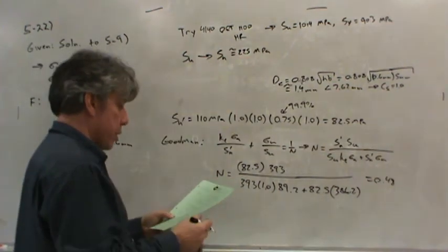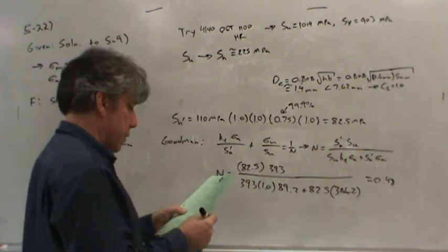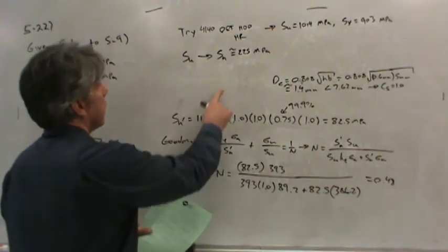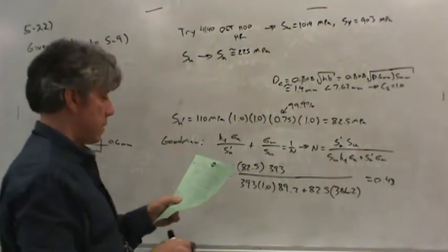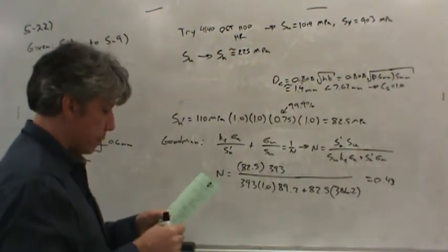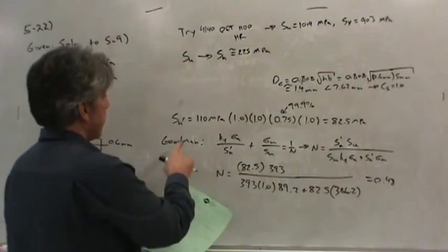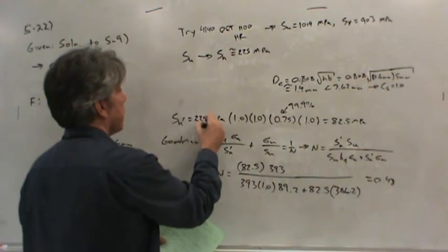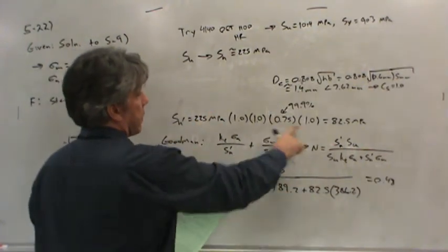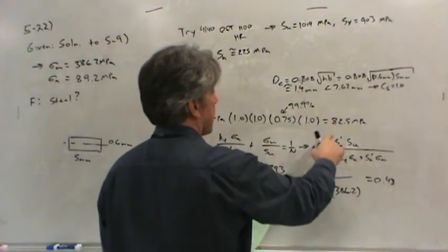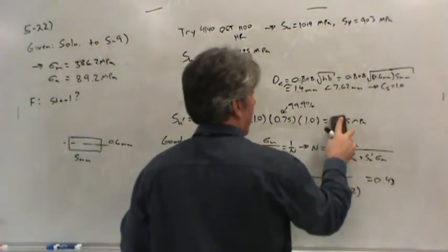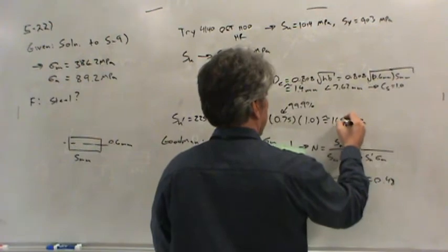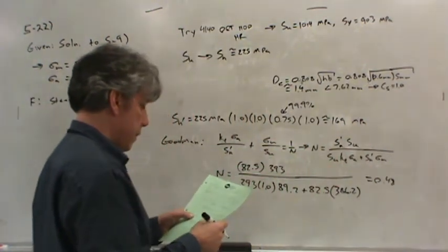So this is quite a bit more strength. This is a little more than twice the strength we had, well, even more. We had, what, 82? No, it was 110. So we got right at twice the endurance strength. Now to get the modified endurance strength, or the estimate of the actual endurance strength, plug in 225 here. Factors are all still the same because the size hasn't changed. And instead what we will get is about 169 megapascals.